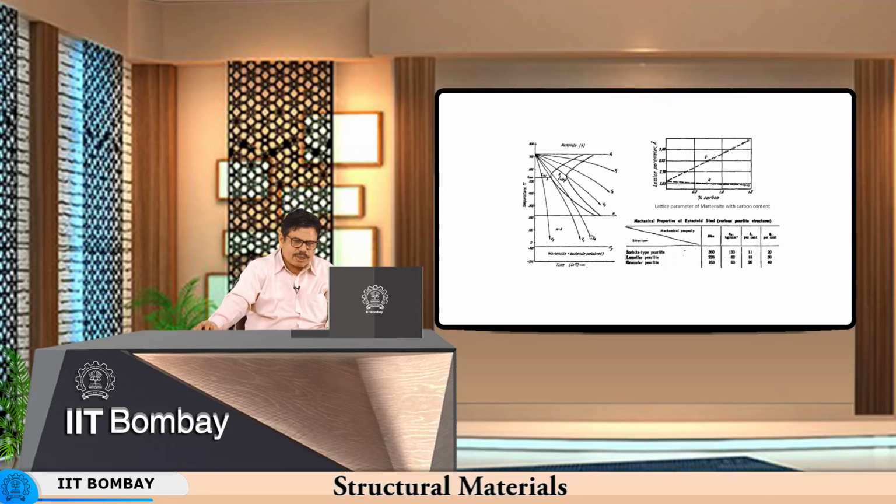So you will have a cementite plus martensite combination being progressively developed. Now here what you will have is austenite plus martensite plus cementite that has been formed already. But then once you come to room temperature, you will have martensite plus so-called retained austenite, because at room temperature you will not go below the martensite finish.